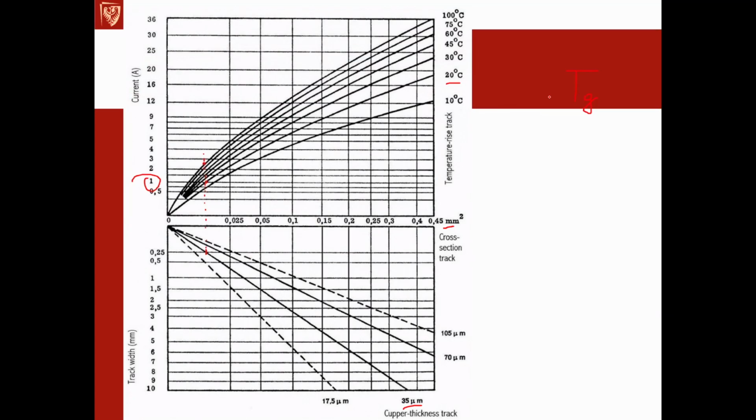In the case of the second note from Jakub, yes, it is resistance, of course. So, simple question, simple answer. The track resistance is responsible for the temperature rise. But what does it mean? I said that 20 degrees is for me the maximum temperature rise, but the reason for this is not the temperature itself, because the temperature is of course one point of the problem, but the temperature results from the power.